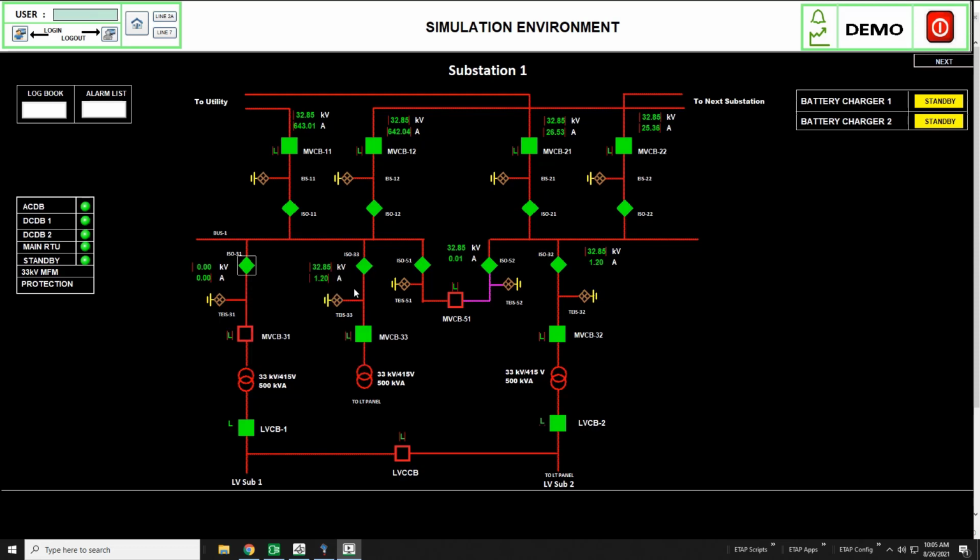Additionally, I'll open the isolator switch here. See how the response is updated. Next, I will demonstrate how the digital twin provides a complete system response. In this case, the power is flowing from the utility into the bus 1 and then being sent to the adjacent substation. If I open the circuit breaker, you will see how the flows coming from the utility are affected, going to 1.16.